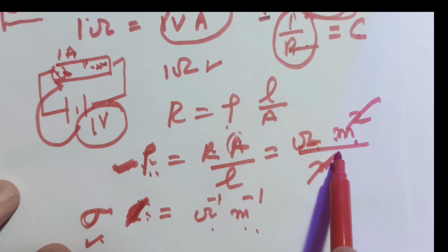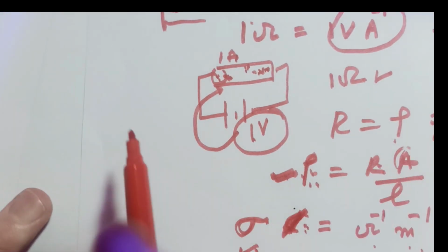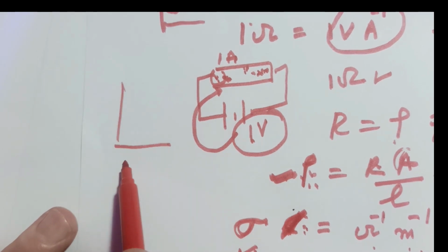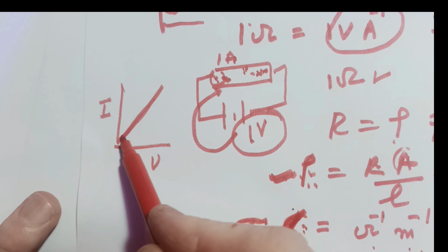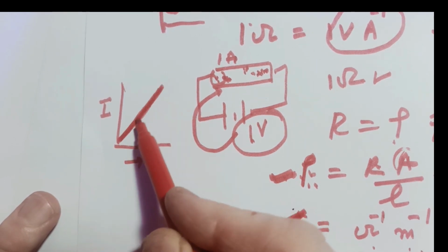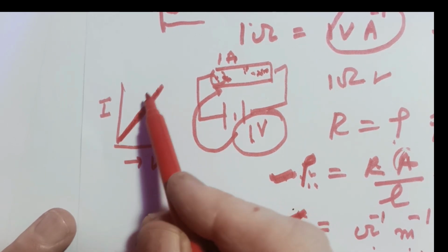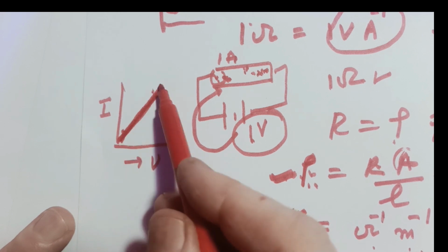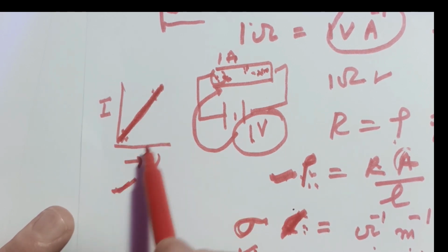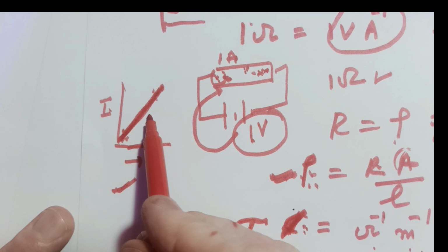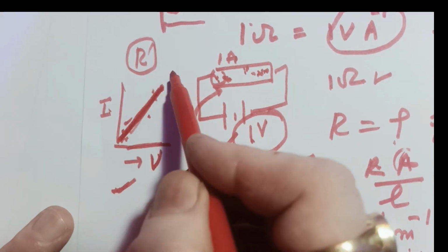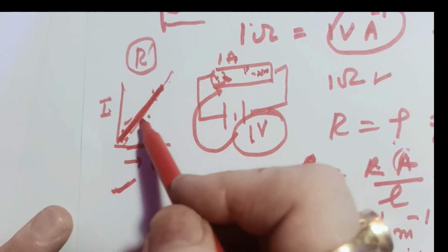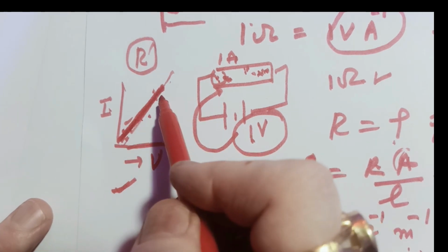Okay. So this is all about Ohm's law, and any circuit which obeys a straight line graph between V and I, that circuit is called a linear circuit. Ohm's law is obeyed and it is a linear circuit if the graph between V and I is a straight line, because then R has only one value. R has only a single value. Single value means linear circuit.